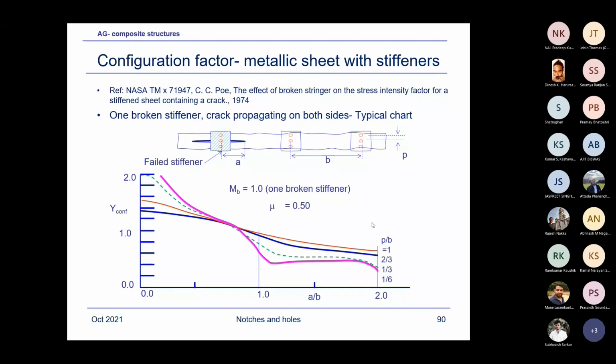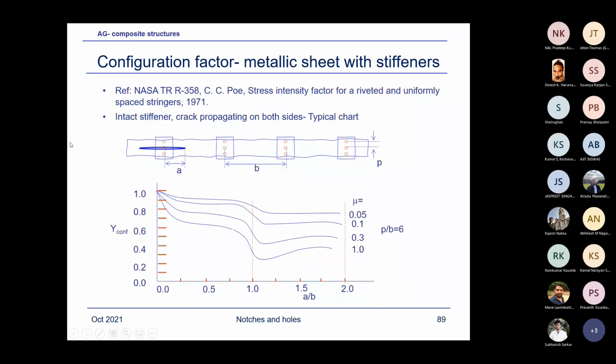Now, there's another scenario where the central stiffener is broken, because that's the real case which you have to consider in your design. This case, no. We have to always break the stiffener. That means this case is not really useful to us in our aircraft industry.